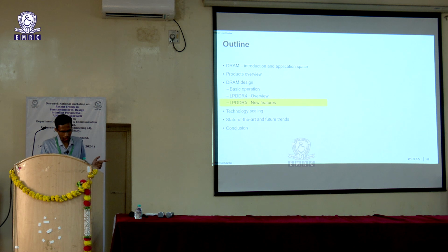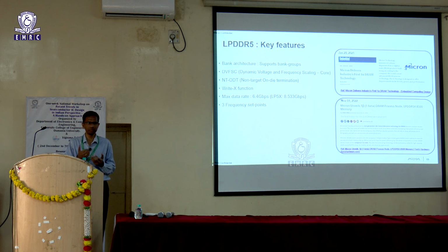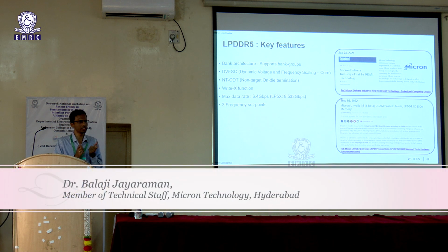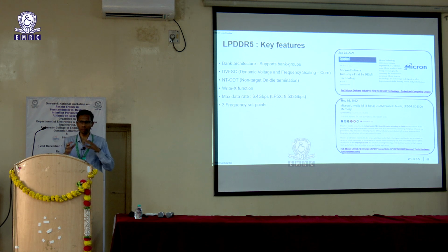We talked about LPDDR4. So, what are the enhancements that you see in LPDDR5? The latest smartphones, the premium phones that you will have, come with LPDDR5. So, here the bank architecture, the architecture diagram that I showed earlier had multiple banks, maybe 8 banks, 12 banks, 16 banks. So, here there is a slight modification. Instead of arranging all as a single group of banks, you have multiple groups now. So, you will have 4 banks in one bank group,